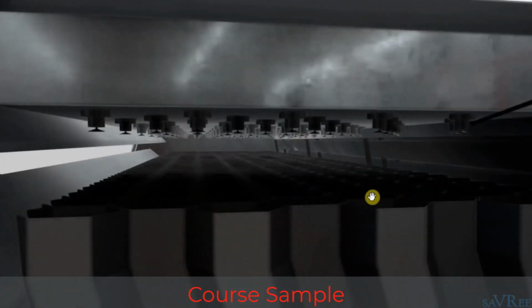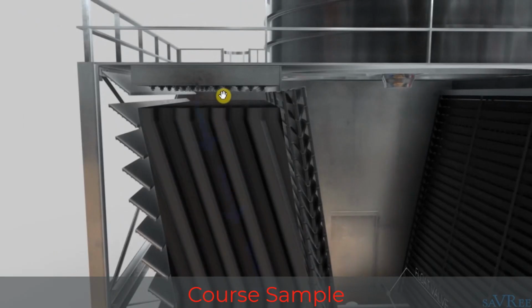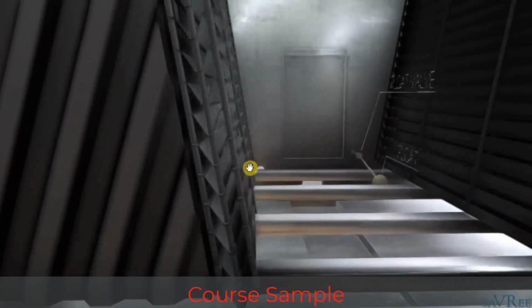We can see the fill is this black section here and it's hexagonal in shape. The fill is effectively a heat exchanger. So the water comes down through the nozzles into the heat exchanger and then it will drip down due to gravity and it will go into the base of the cooling tower.